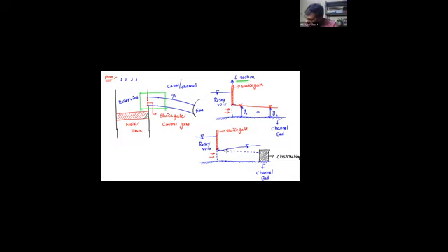So come on, now you tell me, is it a uniform flow here? So my dear student, what is the depth of flow here? The depth of flow here is y1 and the depth of flow here is going to be y2. In the earlier case, y1 is equal to y2. But in this case, y1 is not equal to y2, which means the variation of depth with respect to space is not equal to 0. Then we are going to call it a non-uniform flow.